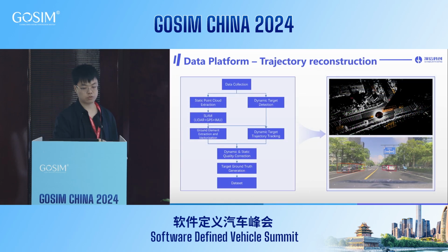And then you want to do trajectory reconstruction. This requires a fusion between LiDAR and vision. So you need to do 3D bounding box type of object recognition, and you need to do tracking. You need to track each vehicle or each traffic participant in order to reconstruct their 3D trajectories. These trajectories can be converted into some scenario definition format, for example, OpenScenario 1.0. And this will give you the ability to run your scenario in the simulation environment.